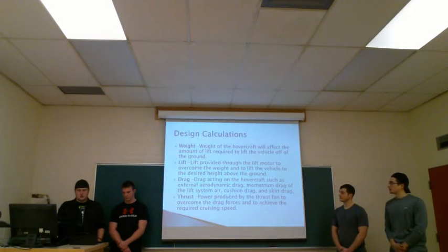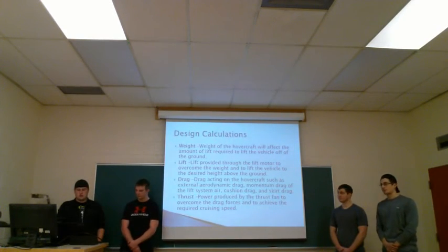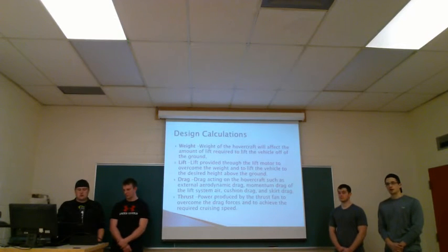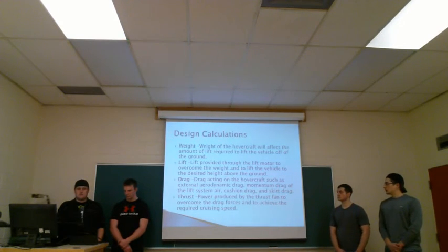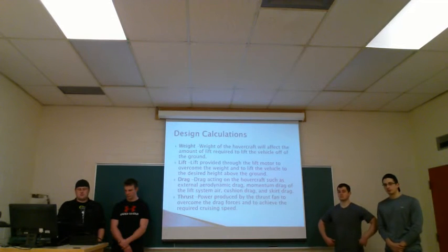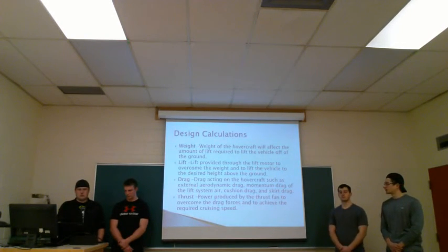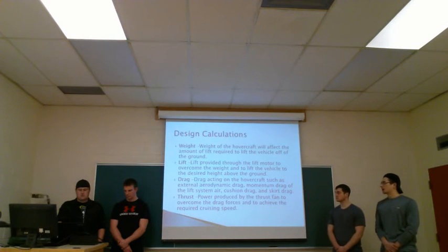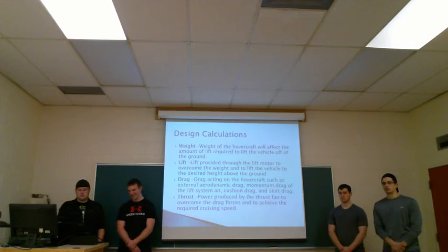So then from there, the lift provided will be based on the size of the motor and propellers that we purchase, and the drag force acting on the hovercraft, such as external aerodynamic drag, momentum drag of the lift system, cushion drag, and skirt drag. This will also help us determine the propulsion motors on the back. And the last one is thrust. The power produced by the thrust fans will overcome the drag force.